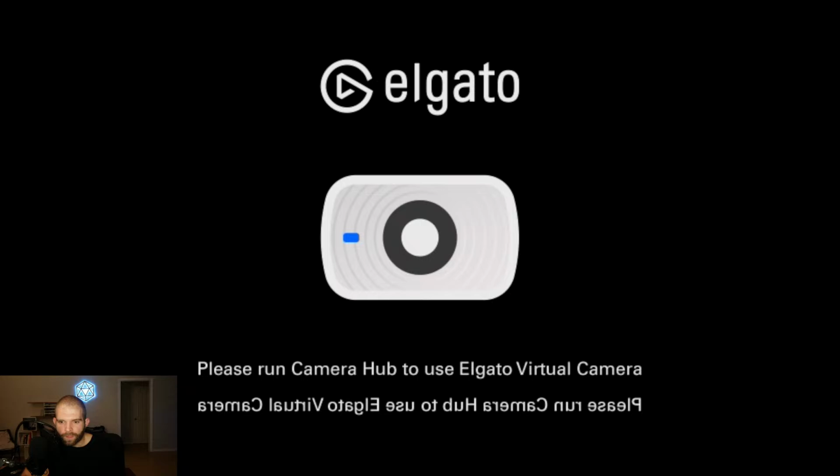So I'll try first with the depth because we're actually able to use depth once more in this render pass, meaning we can use the data not just of the image itself, but a secondary image that presents information about what's close to camera, what's far away from camera, which is just more geometrical information. So for pass inputs, we'll do color and depth. Enable the Z pass. Yep.